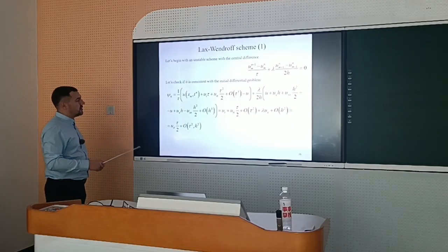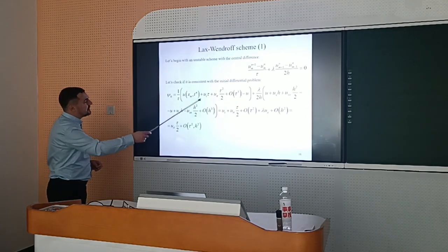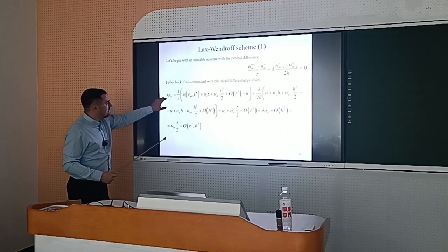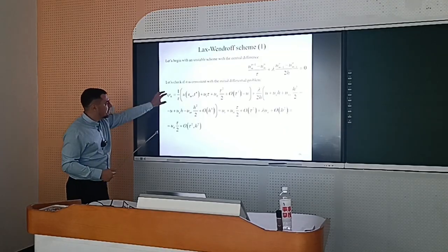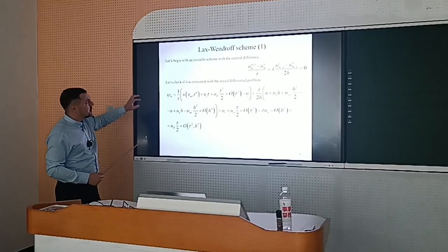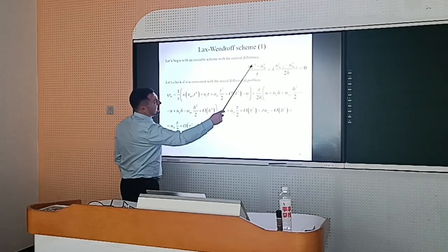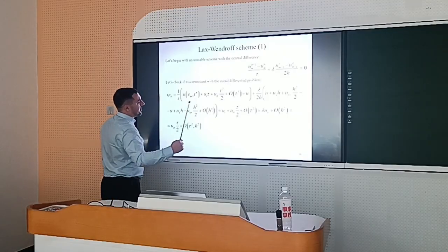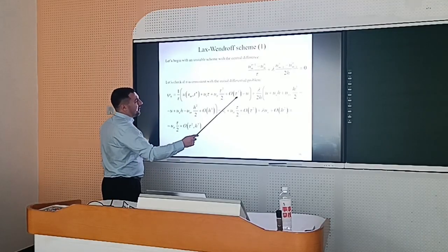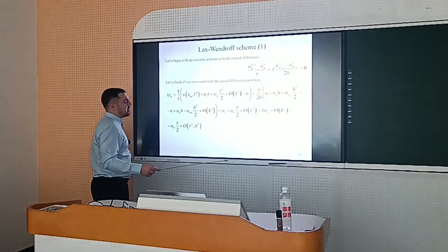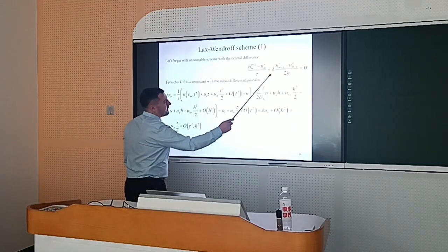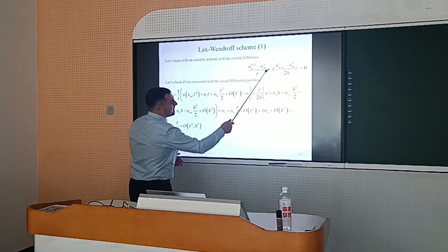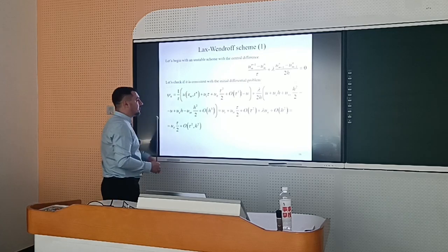For that, we must first of all check the consistency of the numerical scheme. So psi here is the same as delta f on the previous slide. This is the truncation error. Again, we use Taylor series expansion for this n plus 1 here. It's a Taylor series expansion in time, minus u, and u and u will cancel out. We also use Taylor series expansion for this term and for this term, but in x, because m is the spatial index and n is the time index.